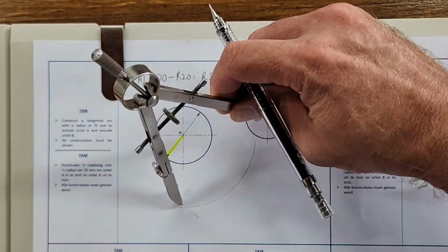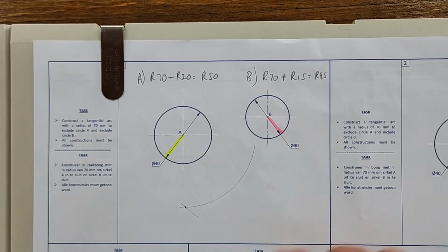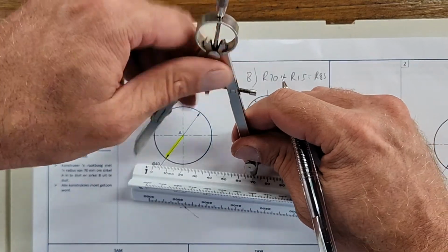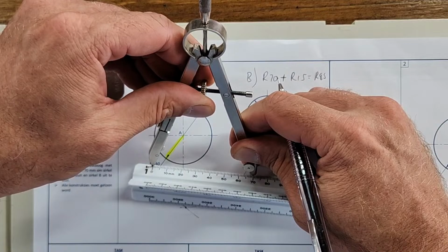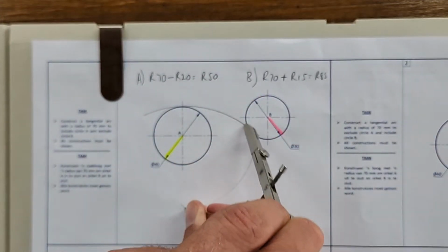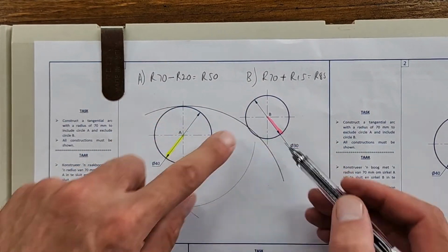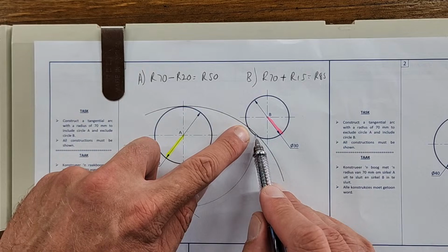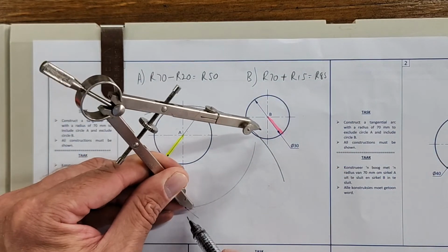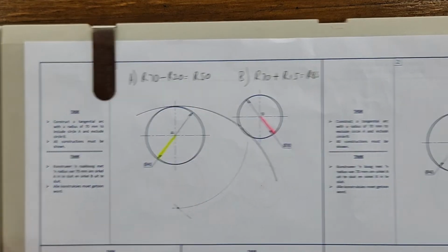From the center, an arc. Right here at the end, that's your center now for a radius 70 arc to be inclusive and exclusive. So go back here, set that to 70, and let's hope. A little bit of accuracy got lost there, but that one is inclusive, that one is exclusive. Please, if you find a mistake like that, rub it out. Just do a slight adjustment here to rectify that. Okay, I'm going to go on to the next one.